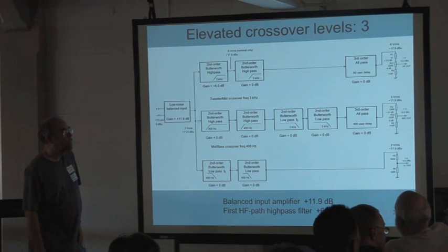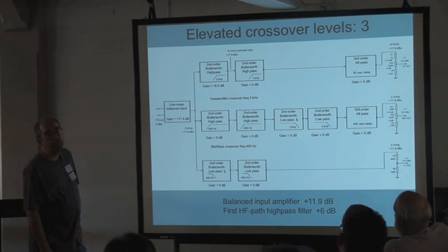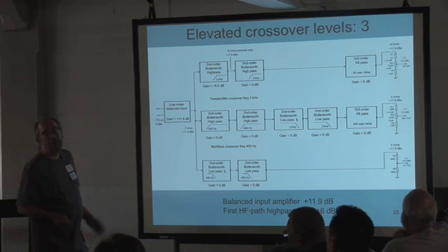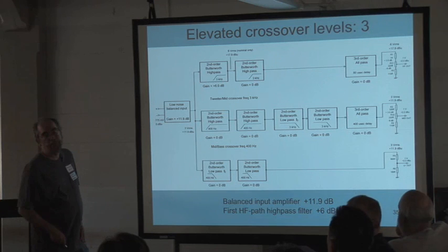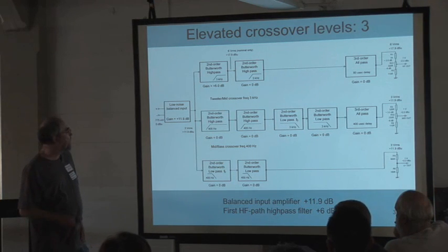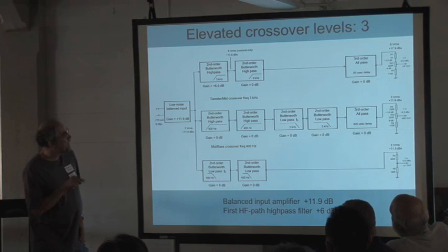Did you relate the mid by 400? That's right, relative to the LF, yeah. So your tweeter is just a delay between that and the mid. That's right. The assumption is that the LF is gone by then. It's 480 to your lower frequency. Well, the assumption there is that by the time you get up to that kind of frequency where that matters, the contribution from the LF path will be negligible. It's a 4th order filter, 24 dBs per octave. There's going to be very little there.